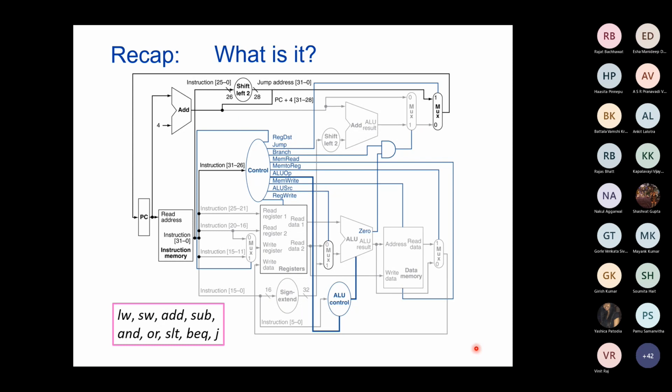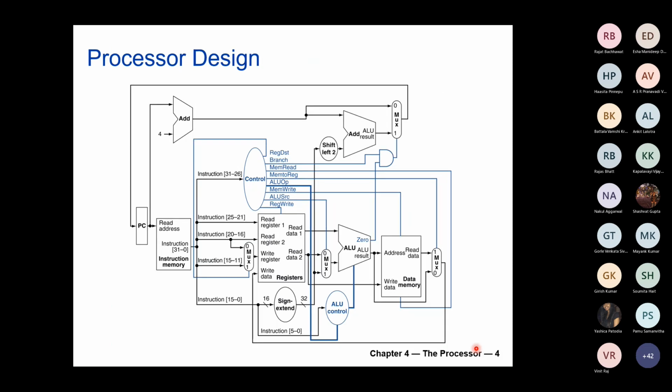So remember that in MIPS instruction, what are the various steps or what various cycles? Instruction fetch and decode, register reading, ALU, and write back. Memory. After ALU, memory access and then write back. And instruction decode and register read, that can be done in one phase. Remember?